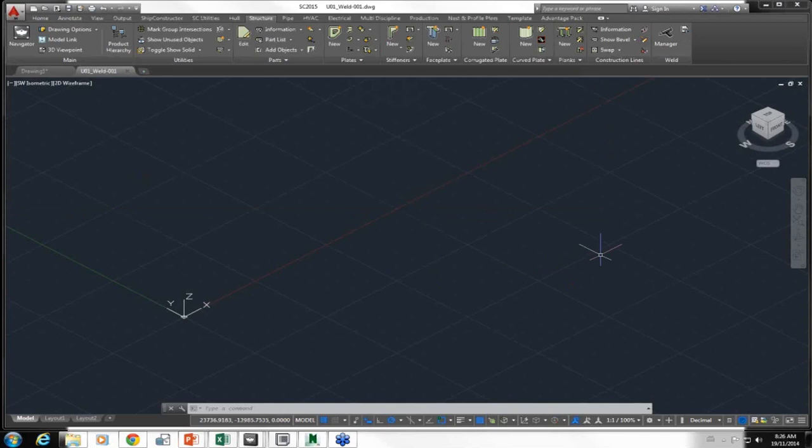So now for weld, the tools that I'm going to be using on the ribbon are under the Structure tab, and on the far right there are only two. It's the Weld Manager and the Update Drawing. And Update Drawing, in fact, is the exact same Update Drawing command that you'll find on the Production tab as well. This goes back to our model where we create in the Weld Manager, save to the central model, and then update into our Weld Management drawing.